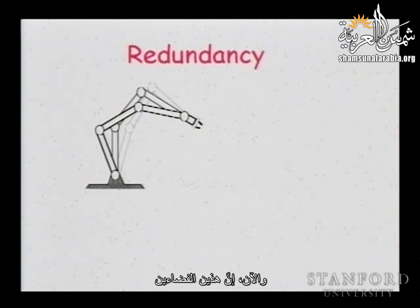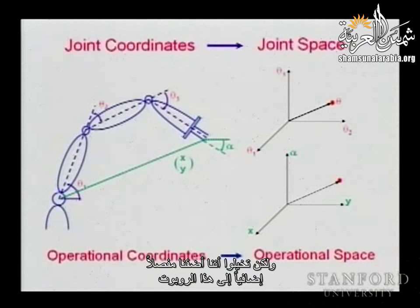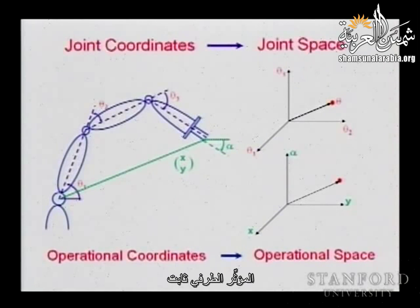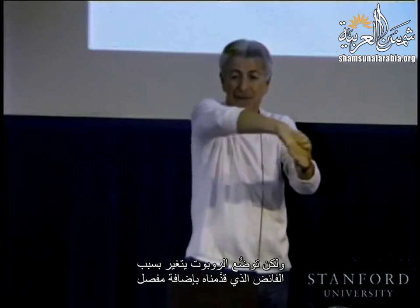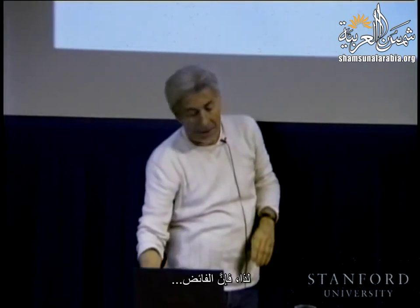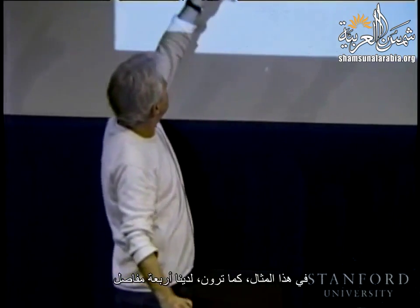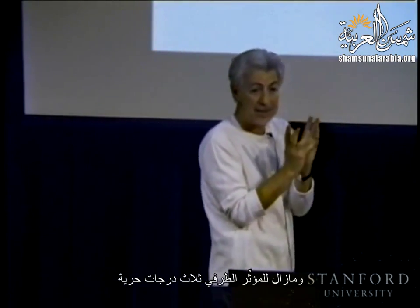Now, these two spaces, the first space fully describes the configuration of the robot, but imagine that we add one more joint on this robot. The end effector is fixed, but the robot configuration can vary because of the redundancy we introduce by adding one more joint. So redundancy, in this example here, you can see we have 4 joints, and the end effector still has 3 degrees of freedom.